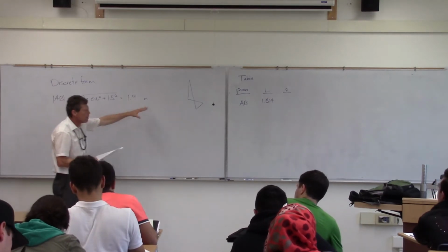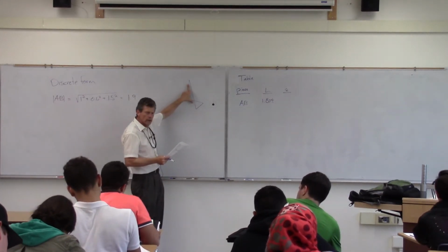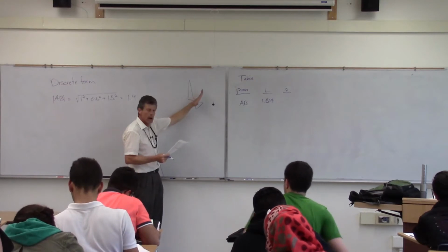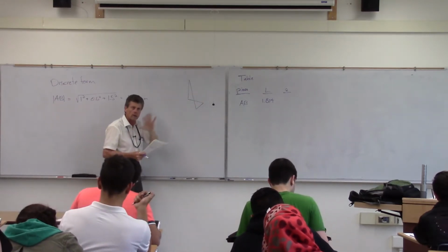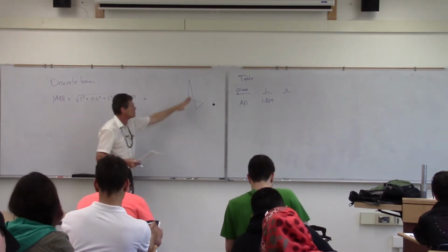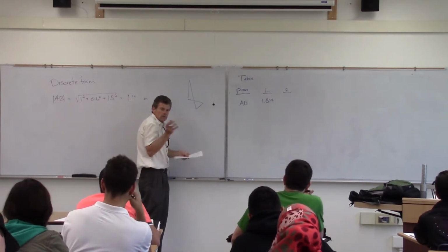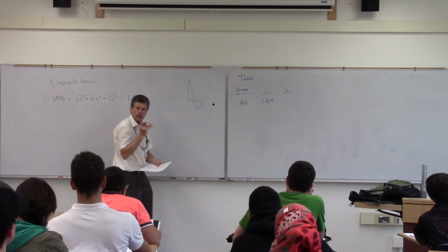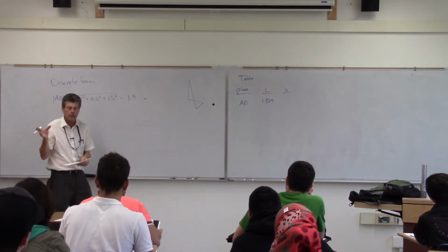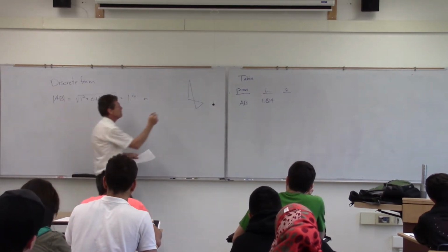Okay, so now we're looking at this piece AB. What we want to do now is find the local centroid of that particular piece. Because it's at an angle, the nice thing though is, since we know it's a straight piece, we know that the center of gravity of that particular linear piece is going to be in the center.